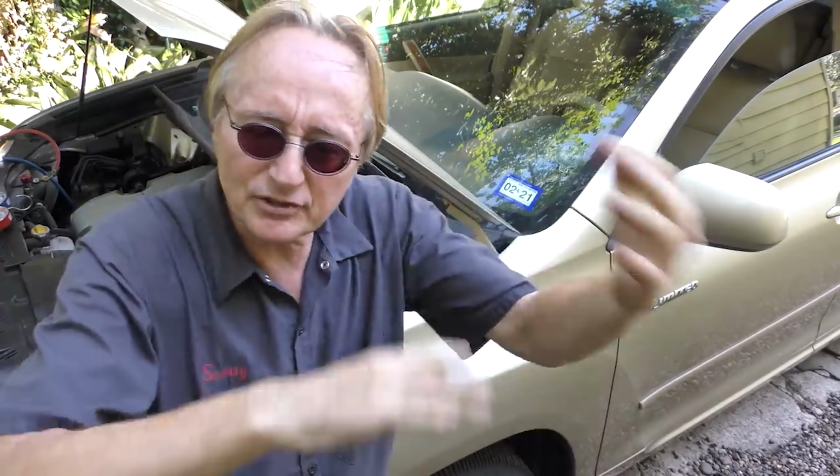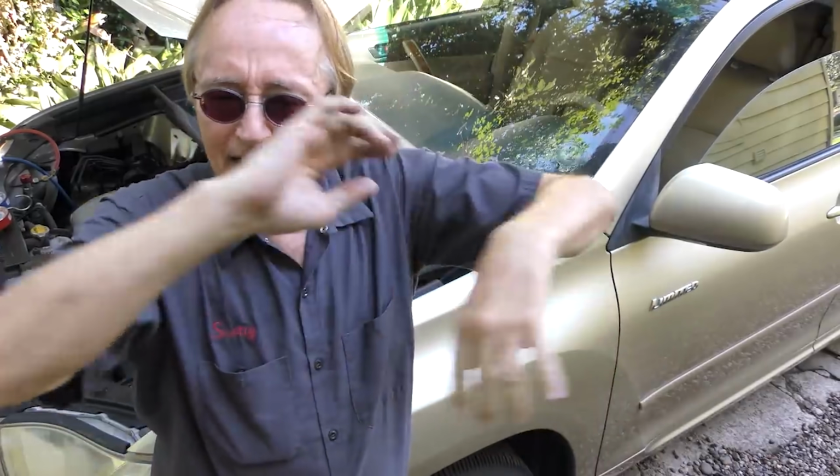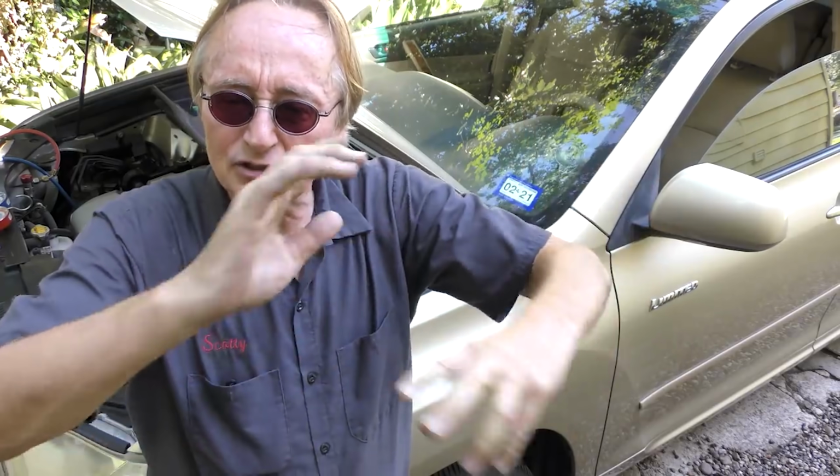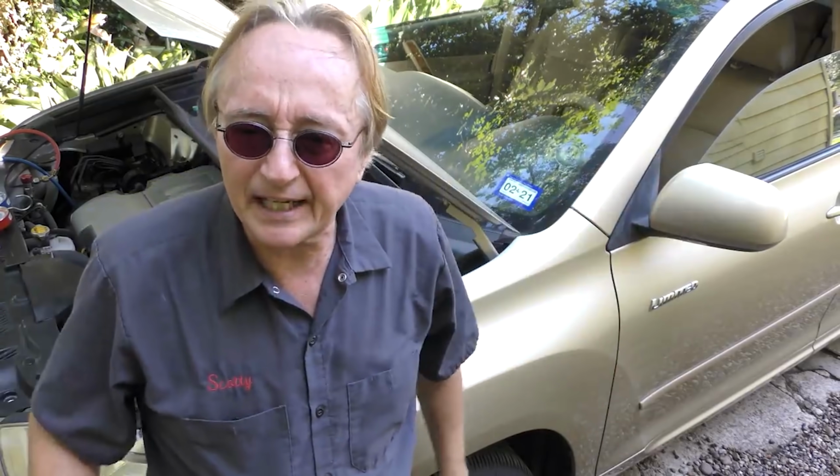But the compressor's still spinning. I'm guessing on this baby, the compressor's just worn out, not sucking and compressing correctly, because the high side should be higher. And if the high side doesn't compress it enough, you won't get high enough pressure to cool it down. The low side can stay too high because the compressor isn't sucking it in fast enough. Seems like a compressor failure to me.